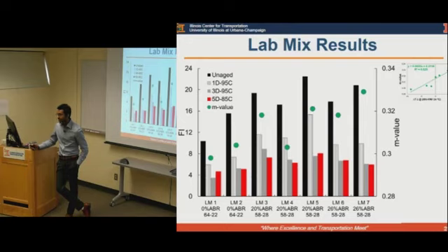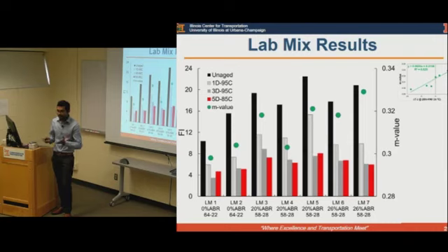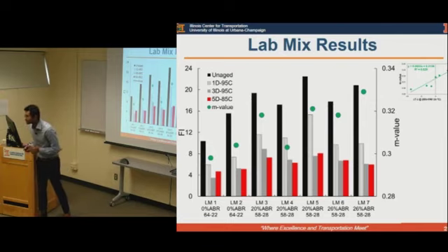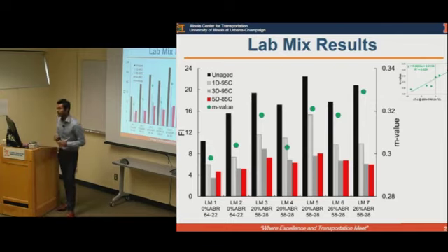So this is something which we need to answer. For example, if chemistry is exactly the same, it is expected that it should perform the same, keeping all other factors the same, like mix design factors and all those things. But that doesn't happen in reality. The chemistry of asphalt binder doesn't remain the same. But what's more important then? Is it the chemistry or the performance at the end of the day? Of course, the performance is important, but chemistry is somehow associated with it.